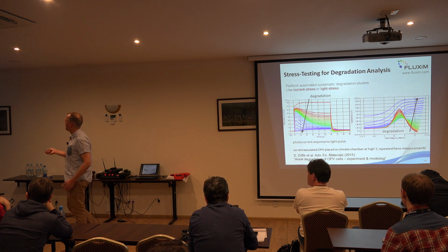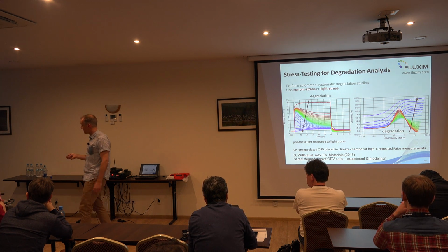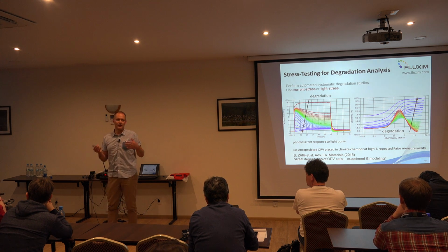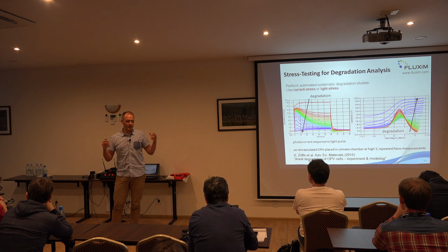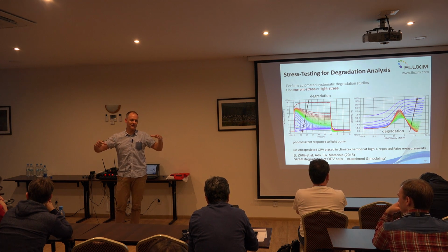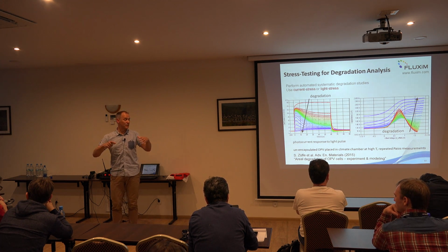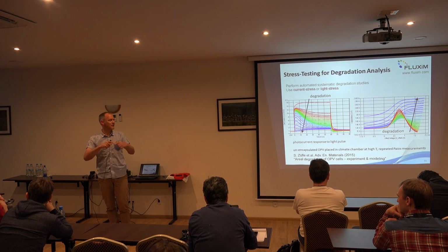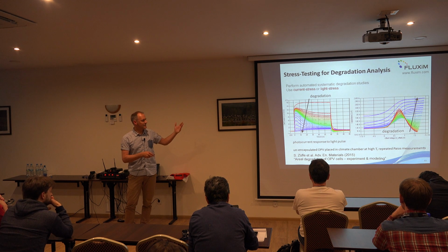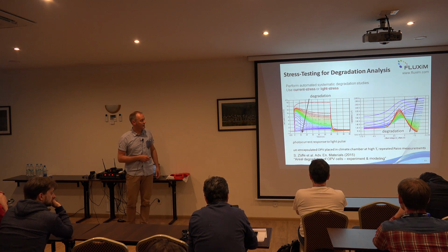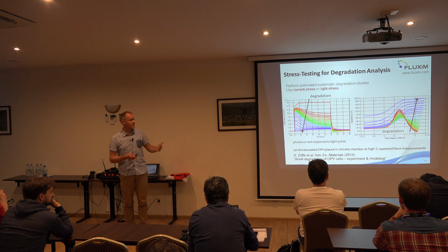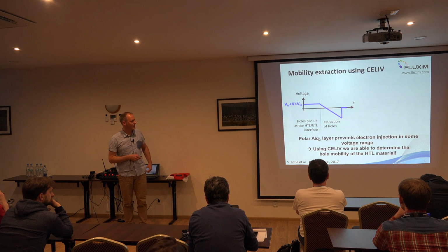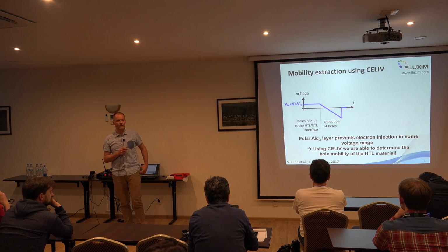And we have quantified all this in a complete picture and found that the aluminum cathode starts to oxidize from the boundary. So the humidity penetrates from the side, and effectively the solar cell degrades from the boundary to the center. And yeah, this is a nice comprehensive study where we combine these measurements and modeling. Okay, but let's go back to the OLED.